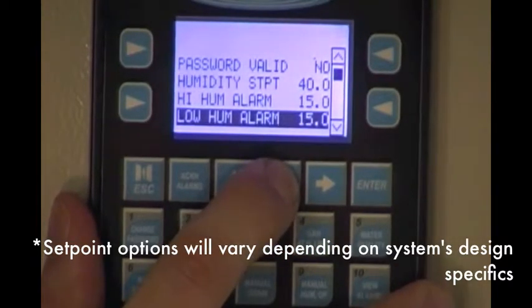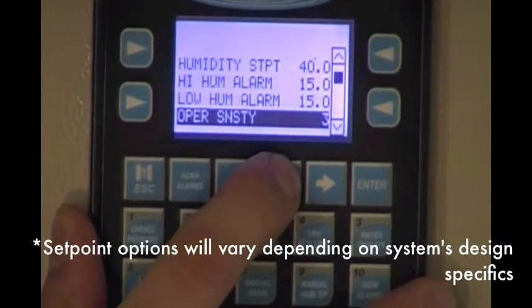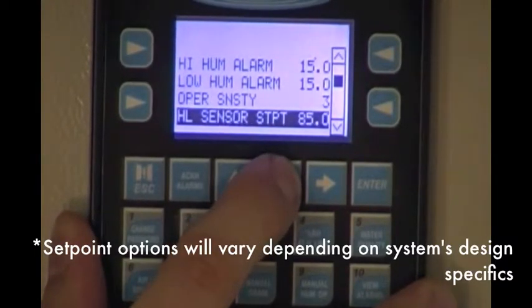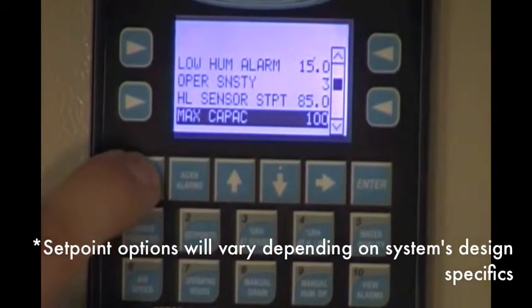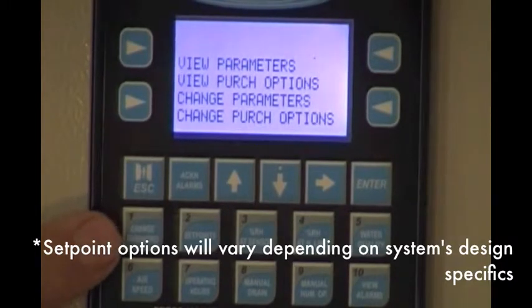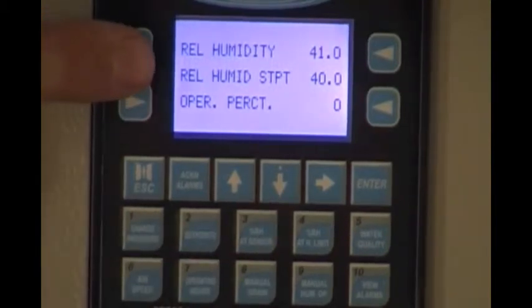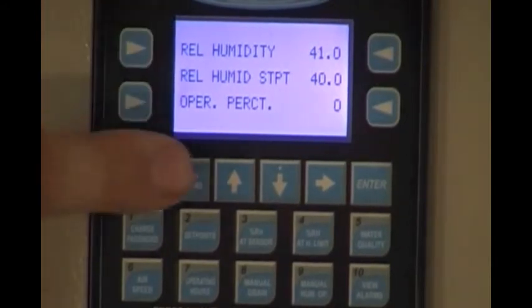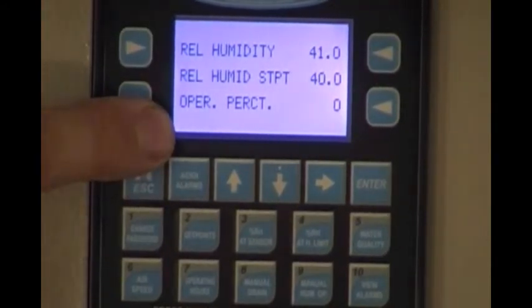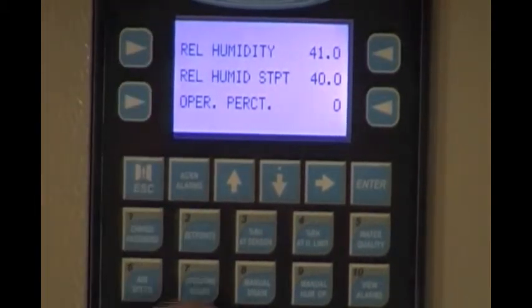In this particular example, we have a humidity sensor, so you may set your humidity set point, your high humidity alarm, your low humidity alarm. You have operating sensitivity and high limit set points. We will give an example of changing your humidity set point to operate your system. In this example, we have a current humidity set point of 40. The relative humidity is 41%, so we have an operating percent of 0. We will now change our humidity set point to 50 to engage our system.